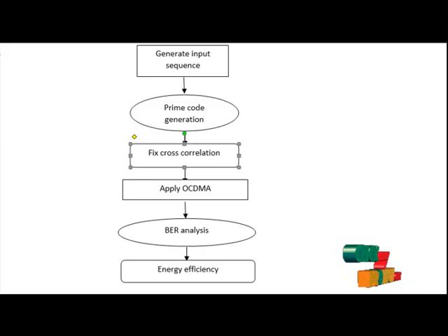If the signal matches the modulation code, then the correlation function will be high and the system can extract the signal. Correlation is a method of measuring the similarity of 2 waveforms as a function of a time lag applied to one of them. If the prime code, the double weight code, has nothing in common with the signal, the cross correlation should be as close to 0 as possible. This is referred to as cross correlation.